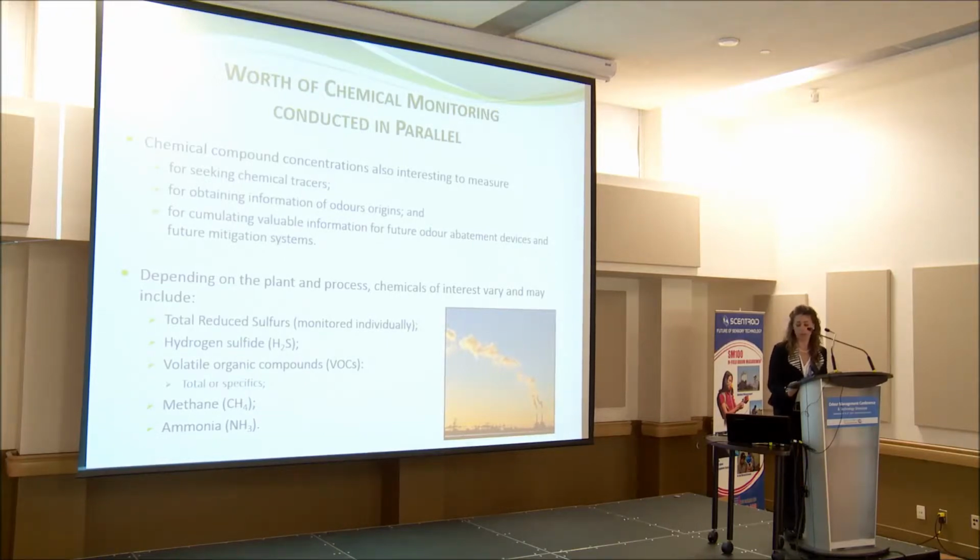So valuable chemicals, and yeah, you can also try to derive a tracer. Continuous monitoring of odors, it's not yet something that is ready to install, I believe. But you could probably try to find a chemical tracer that actually correlates with odor concentrations. Landfill sites, for example, it's not H2S. I've done that previously. It's not H2S. It'll be methane or VOCs. Most often, there are no correlations with H2S.